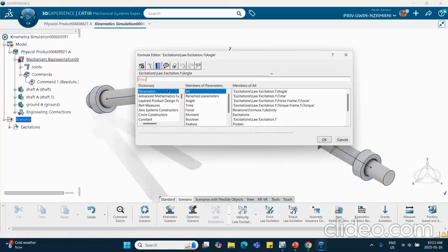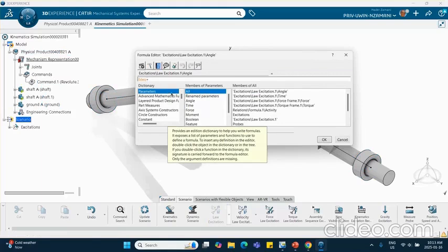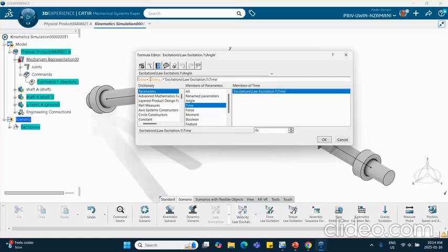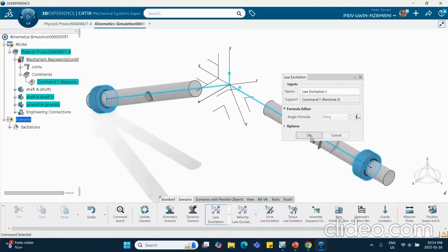So for example, you can say this is equal to, obviously, 0 plus, let's make it 360 degrees per second, so 360 DEG_S times time. Now you could have typed here 60 turn per minute and then times that. It's okay. Now there's physics here because we're specifying the velocity, or the angular velocity, of this shaft. Okay, revolute joint. So we say okay and say okay.